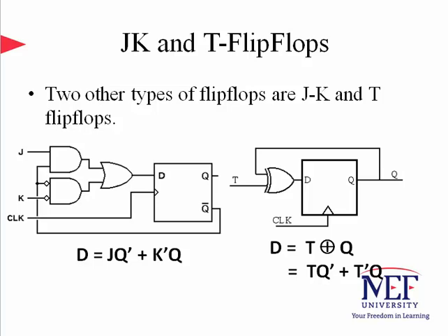First off, I would like to remind you that a generic flip-flop serves 3 basic missions besides storing a single bit for a digital system. It can either set the output to 1, or reset it to 0, or complement the output. The JK flip-flop is the most general form of all, and it's capable of performing all 3 basic functionalities.